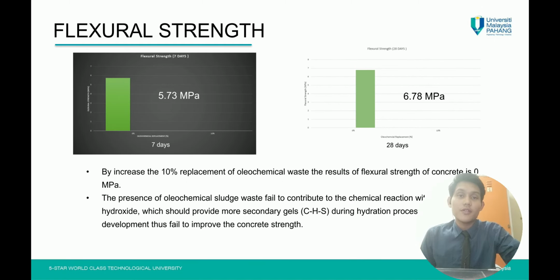So for the flexural strength test, for the 7 day is 5.73 MPa, and for the 28th day is 6.78 MPa. For the 10% it is 0 for both. By increasing to 10% replacement of oleochemical waste, the flexural strength of concrete is 0 MPa. The presence of oleochemical sludge waste failed to contribute to the chemical reaction with the calcium hydroxide, which should provide more secondary CSH gel during the hydration process in strength development. Thus it failed to improve the concrete strength.